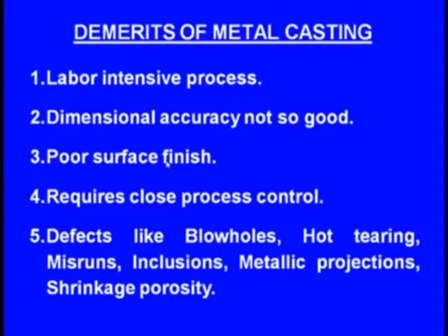Next one, the casting process requires close process control. Means the moulding medium has to be prepared very carefully. The moulding sand contains the base sand, and the clay and the moisture. This clay and moisture should be controlled very carefully.